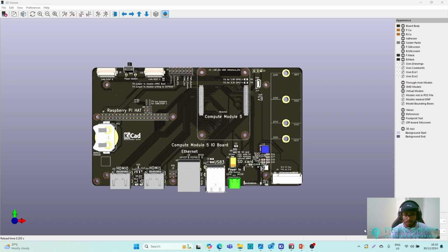What you can do is simply look into the CM4, not CM5, but the CM4 IO board, and they have a buck converter there. You can use the same design here and add some sort of power switching between the type C and the other power input, since when both are available you should only use one. With the power switching or power selection circuit, you can get your own modified board which can work with 12 volt ports.